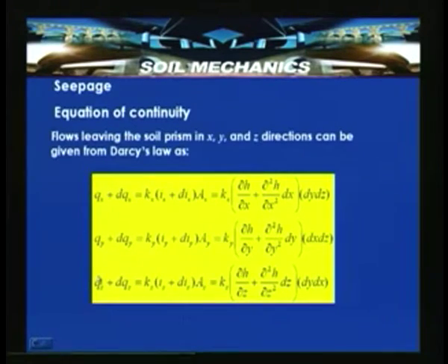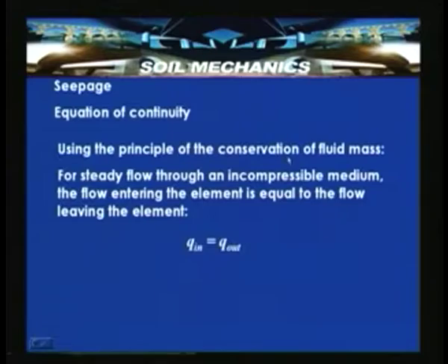So, now what we have got is, by using Darcy's law, flows entering the element and flows leaving the element. Now, using the principle of conservation of mass, let us try to derive the equation of continuity. Using the principle of conservation of fluid mass, for steady flow through an incompressible medium, the assumption is that the medium is incompressible.